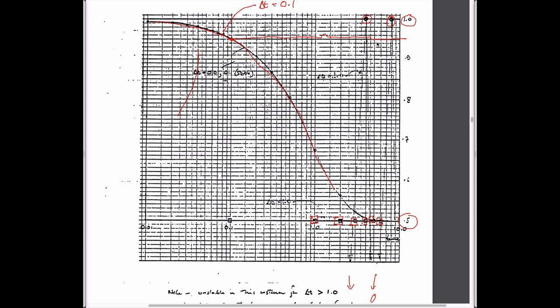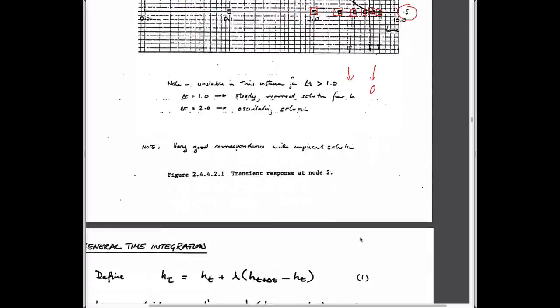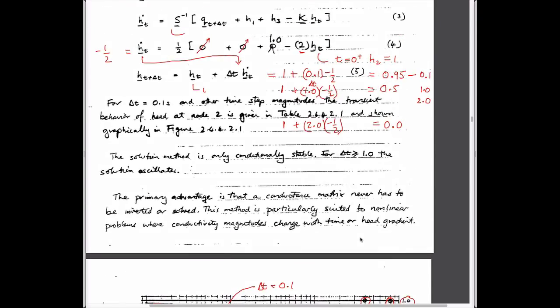And so if you use too large a time step, then the problem you have is that you just get an unstable solution. This isn't so unstable. It's clearly wrong because it's bouncing back between these, and it can't actually have a head which is lower than the equilibrium head in the system. And if you used a larger time step, such as 10 seconds, actually, what would it be? If you use 10 seconds, what would it do? So this was 2.